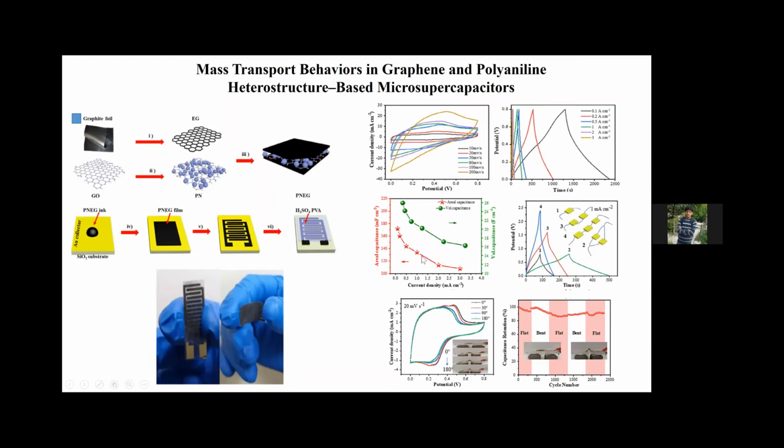And for the planar devices, one beauty is, we can make any kind of connection, whether we add the number of capacitor devices in series or parallel, so that if we want to improve the voltage window, or else we want a higher current, voltage window is limited but the high current, so based on that we can connect it through series or parallel.